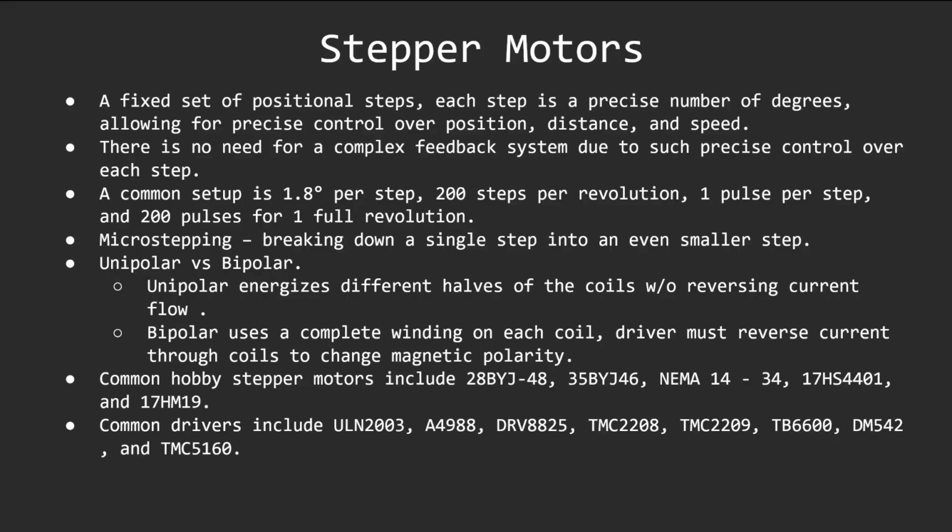We also have a concept of microstepping. That's where you can break down a single step into even smaller steps. There's also unipolar versus bipolar stepper motors. These are fundamentally different, although the operation may appear the same. This has to do with the coils and the actual motor.